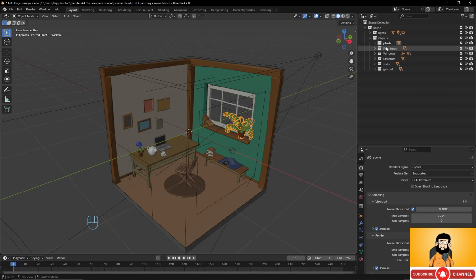And so it's really important to organize your scenes like that, because when you open your Blender file after years, if everything is named Cube and you only have the default collection, it will be complicated to manage. If you have maybe, I don't know, 30 objects that are just named Cube, it will be complicated because you start modeling with a cube very often. So yeah, it's important to organize things.